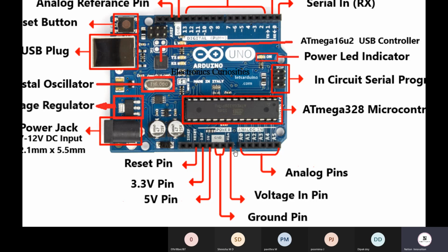In my experiments as well, whenever I crossed this 9 volt supply for this pin, my devices burned out. This is because this pin is not directly attached to a circuit to first drop the voltage down to 5 volts for proper functionality of the board. The track available for this supply is not as big as the one provided for the jack, which is the main reason there are chances of short circuit and burning out because of this Vin pin.